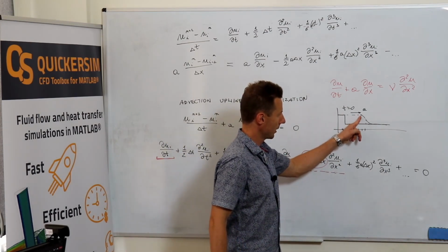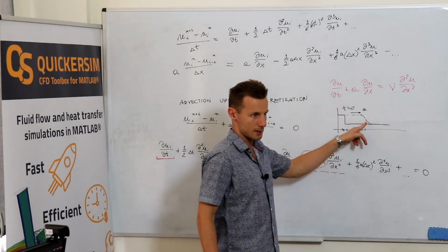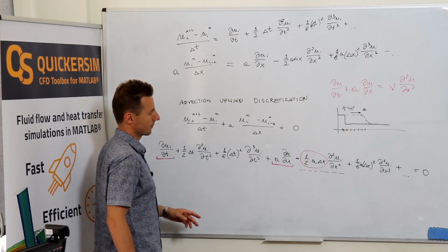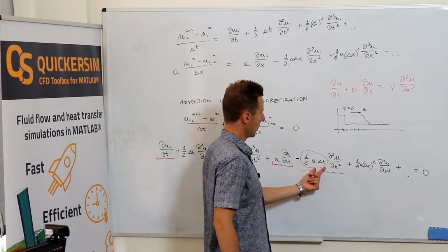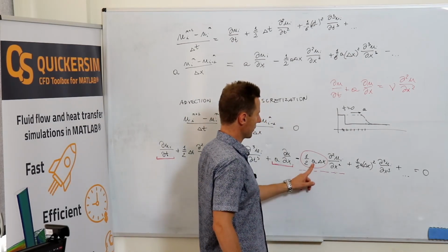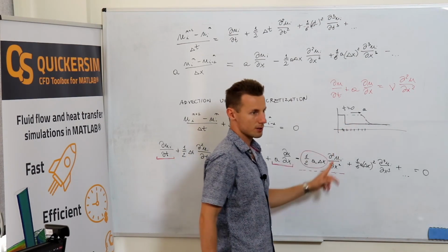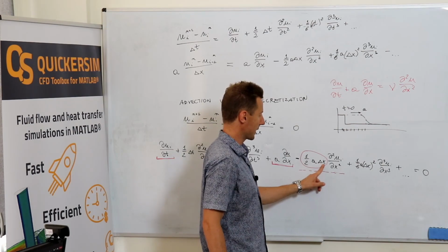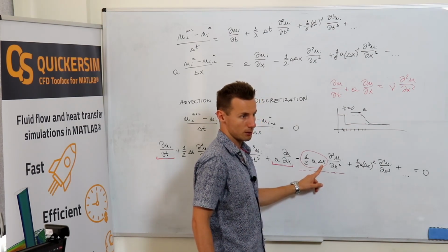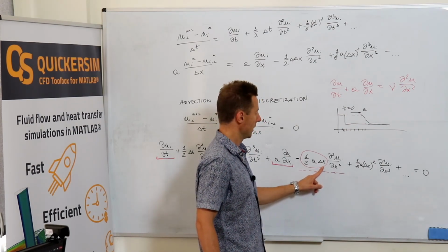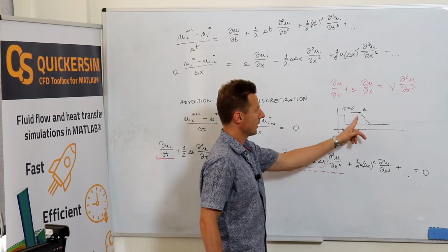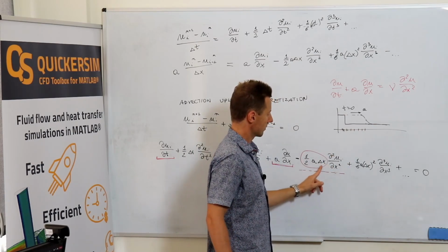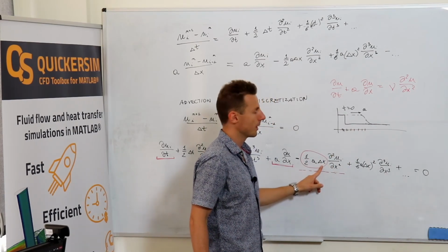Well, so basically, you can observe something like that as the result of the diffusion that you introduce. What's the diffusion? First of all, it's proportional to the advection velocity and the delta x. So you can see how you can reduce that. You can probably reduce this effect by taking smaller space discretization steps.